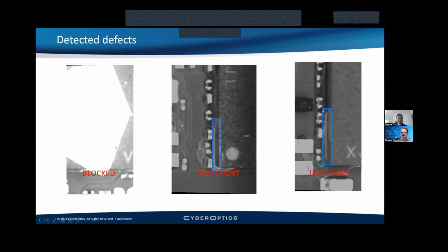One of the problems in inspection has been things like shadows and excessive reflectivity of different surfaces. Does deep learning capture all this? Yes, two things will decide its capability of catching that kind of defect. Basically, we call these variations. The first thing, for sure, is that we need to collect examples of different variations.